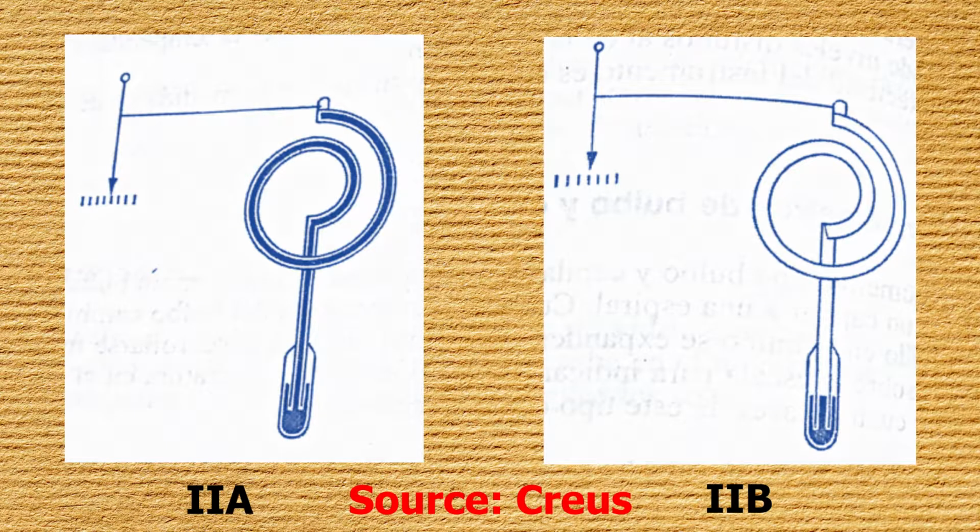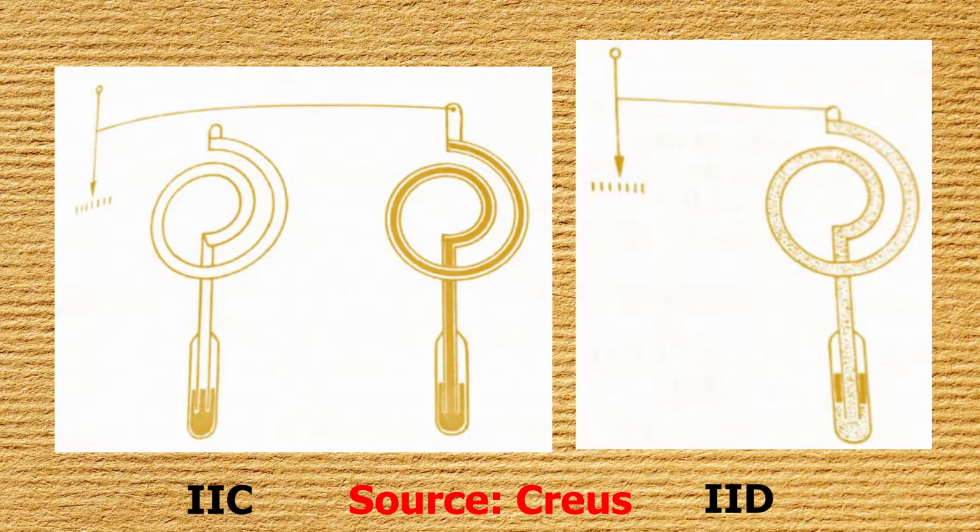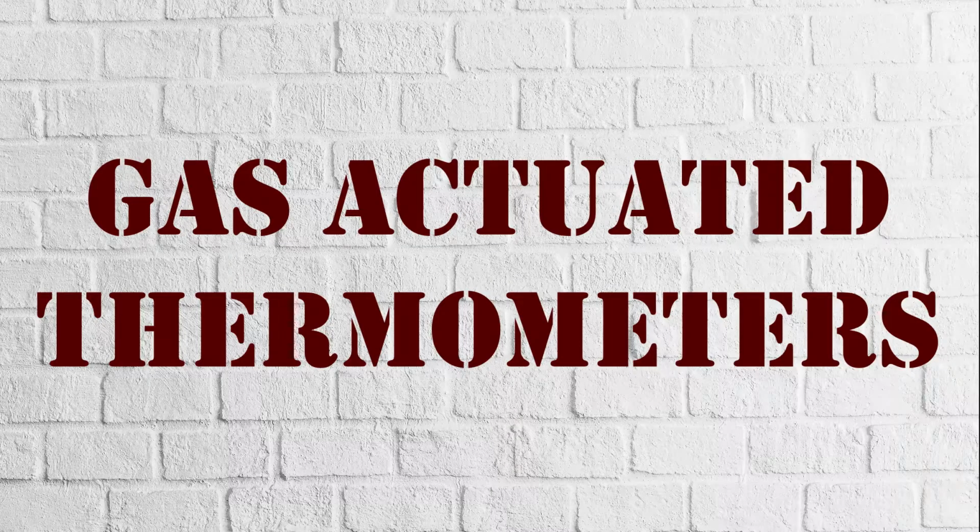In the Class 2A thermometer, if the bulb temperature is higher than the ambient temperature, the capillary and the measuring element are filled with liquid, being necessary to correct the indication in the difference in heights between the bulb and the measuring element. In the Class 2B thermometer, if the bulb temperature is lower than ambient, the system fills with steam. Class 2C operates with the bulb temperature above and below the ambient temperature, and Class 2D works with the temperature of the bulb higher, equal, and lower than the ambient, using another non-volatile liquid to transmit the vapor pressure.